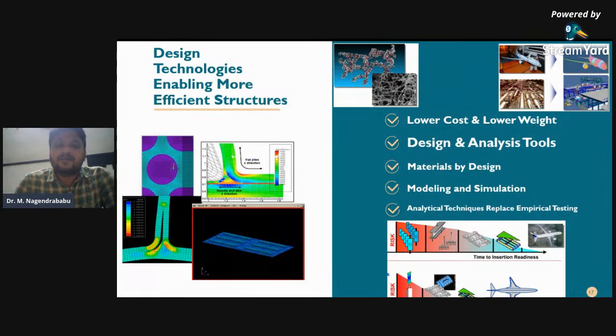Another reintroduction of aluminum to aerospace is found in weight saving aluminum lithium, specifically designed to improve properties of 7050 and 7075 aluminum. Overall, the addition of lithium strengthens aluminum at lower density and weight, two catalysts of aerospace material evolution. Aluminum lithium alloys' high strength, low density, high stiffness, damage tolerance, corrosion resistance, and even weld friendly nature make it a better choice than traditional aluminums in commercial jetliner airframes.